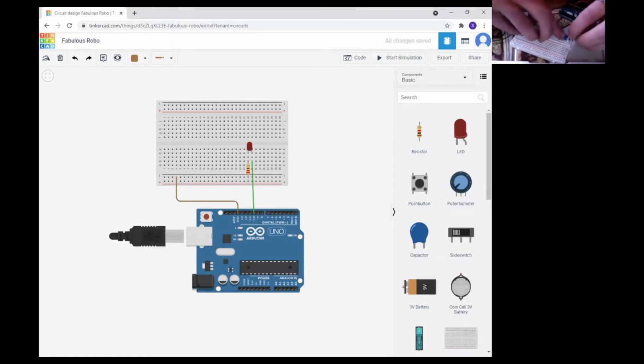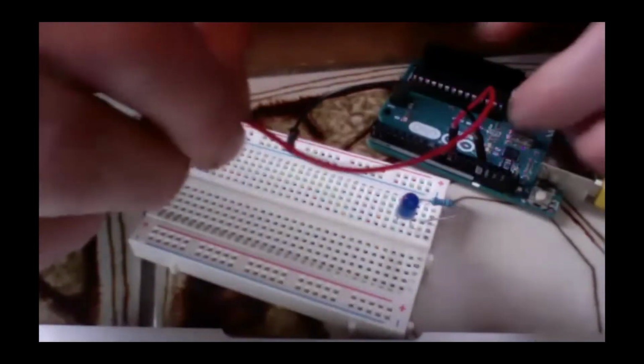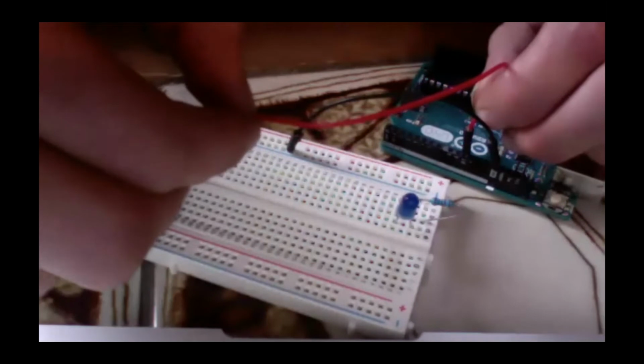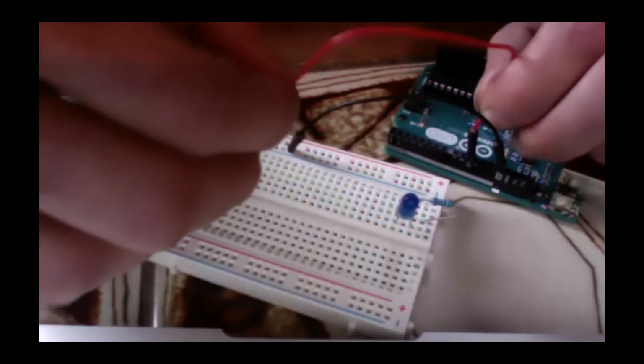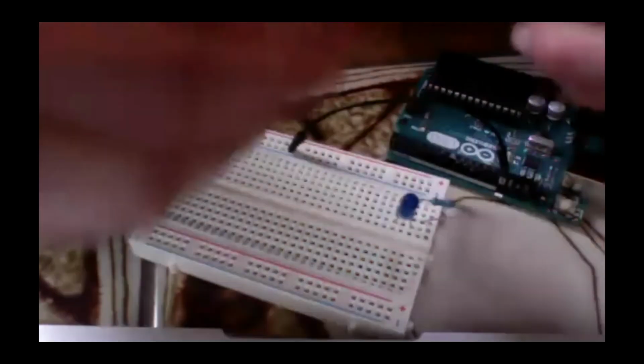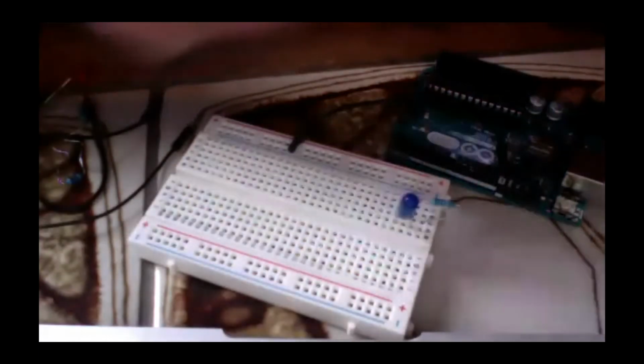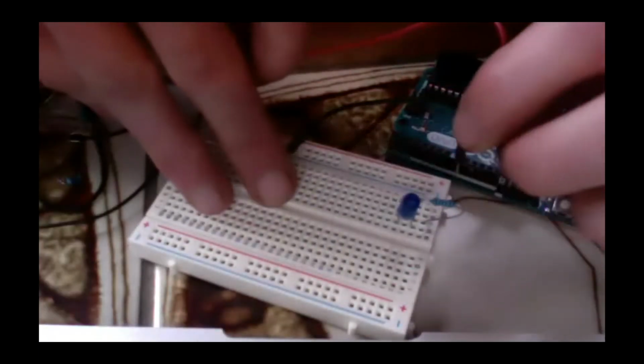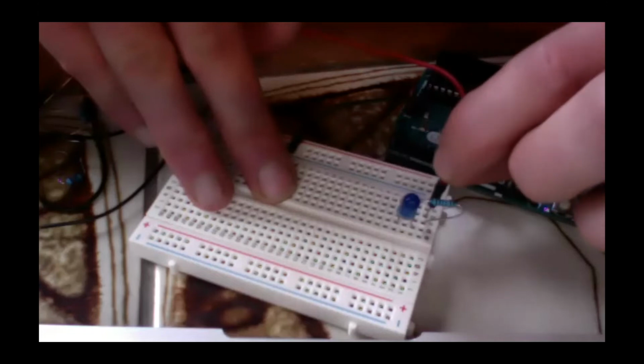And then in the same way that Sophie has connected up this side, we get one jumper wire. If you've got one of any color, this is going to be used for our pins on the Arduino. We take one end and we put it into B1.